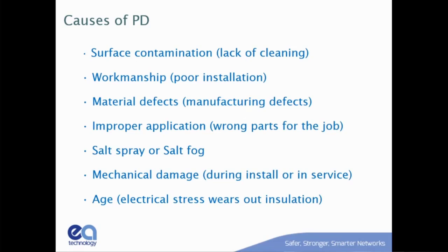And before cold shrink terminations, you had to be really skilled, and there was an apprenticeship and all this to doing cable terminations. And if you didn't know what you're doing, you didn't try to do it because it was too hard. Cold shrink termination, I can go to Amazon and get a Raychem termination. I did. I got a hunk of cable, I got a Raychem termination, and I did it in my garage. I followed the instructions. Well, the instructions say strip back semicon as usual and clean as you normally would, and things like that. Well, if you don't know what you're doing, my definition of stripping back the insulation is definitely not the same as someone else's.